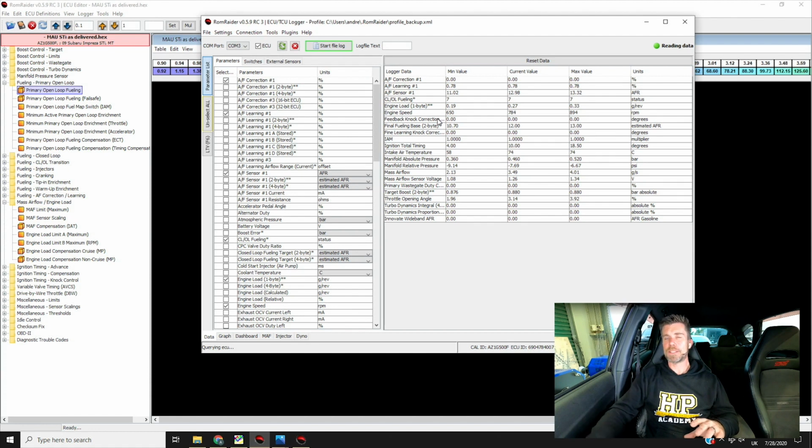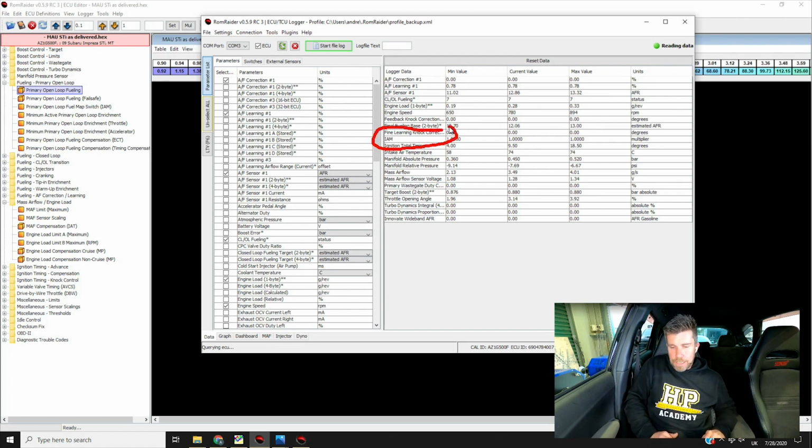So it sounds complex, and if you do want to see that in a little bit more detail, obviously I'm not focusing specifically on that today, the ECU flash worked example in the practical reflash tuning course covers that in a lot more detail. You'll also be able to see it in action. So on that note, we do have our IAM value here, and we can see that that is sitting right now at 1. So obviously, again, pretty good starting point. That's what we'd like to see.